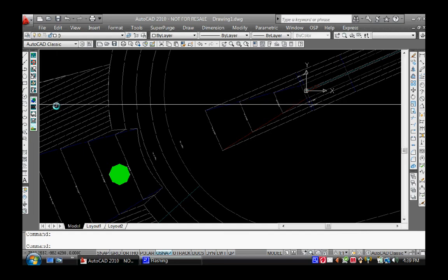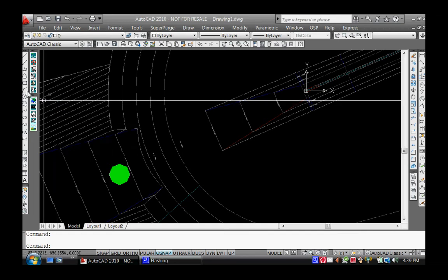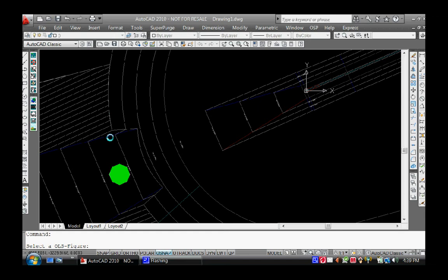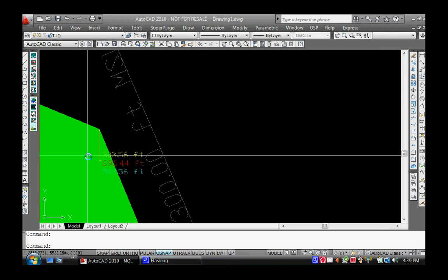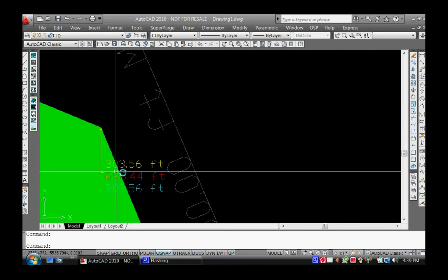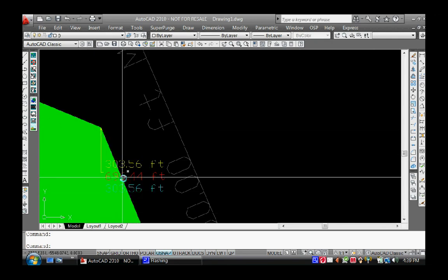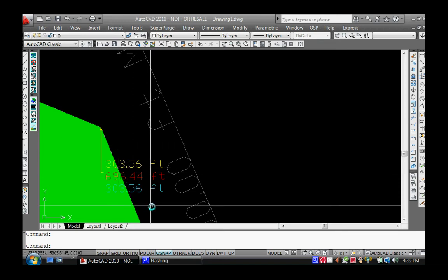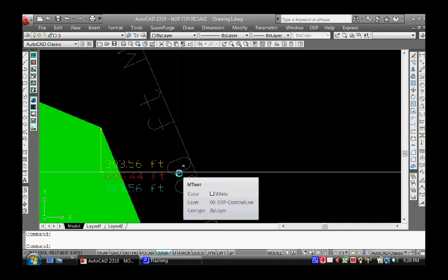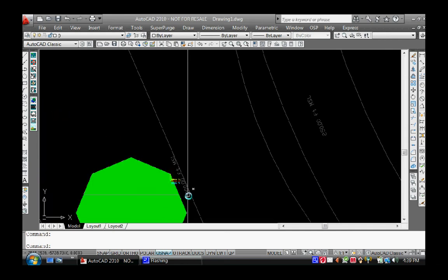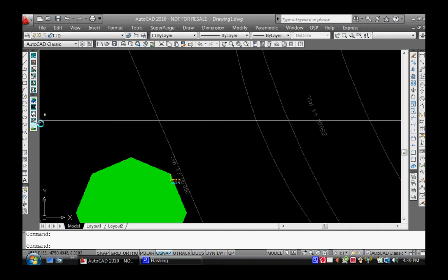It's a top-down view. But what we can do is find out where the penetration is of the nearest portion. So if I click on the actual surface with this tool here, I can zoom in and it'll tell me, okay, at this point, the height of the surface and the object is 303.56 feet, and it's penetrating by 696.44 feet. Okay, and I can actually export that to a really nice table by clicking on Overview Intersection of Objects.